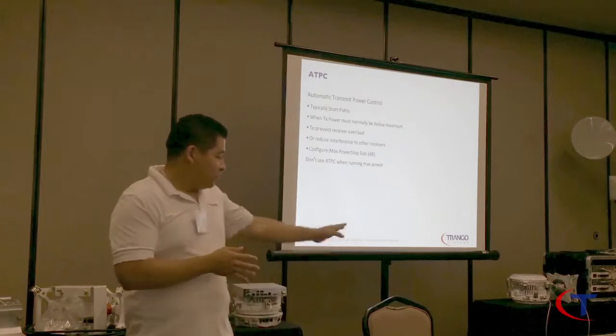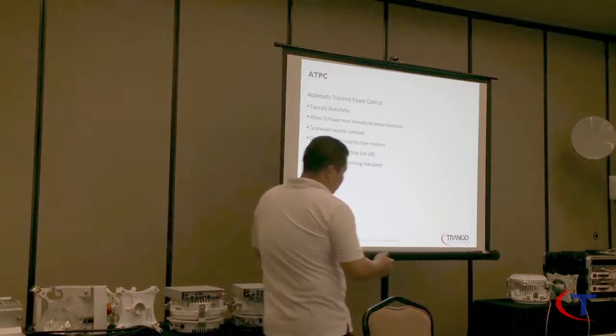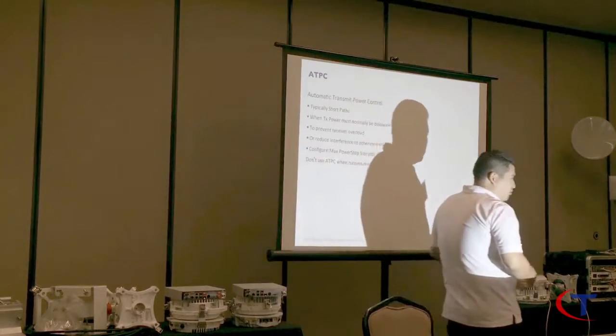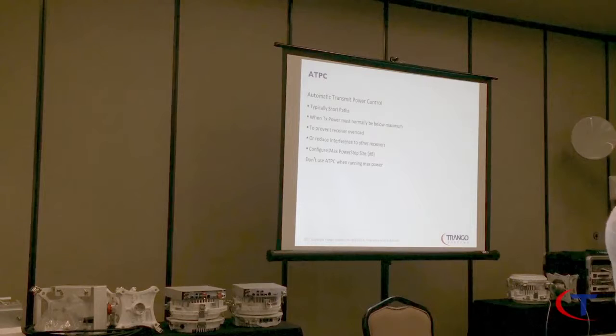For example, in this note that I have for you guys, this is a bench test. This is called the poor man's bench test because we don't have any antennas between them, we don't have anything. But I have a really neat trick for you guys. Right now, if I turn it on, we're going to have a -10, -5 RSSI in this link. That's not really good. The radio needs to operate at least at -24, we recommend -30. That's as high as you can actually run it. Anything below that, you're going to see BERs and FDRs. So try to keep it at -30, they're usually engineered for -30 and above, -34.